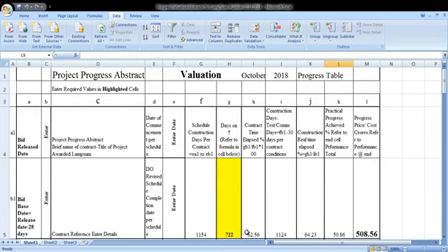So a lot of work is done. You can say major portion of work is done prior to work start or when site opens. There's no very hard and fast rule. It depends on, means you have complete breakdown of quantities. Based on that breakdown, you have unit rates. You can approximately find what's cost of work done on this, and that's the purpose. So it's not actually detailed quantity engineering for valuation purpose. It is indicative and based on only the worked out quantities. That's a very important point in this.